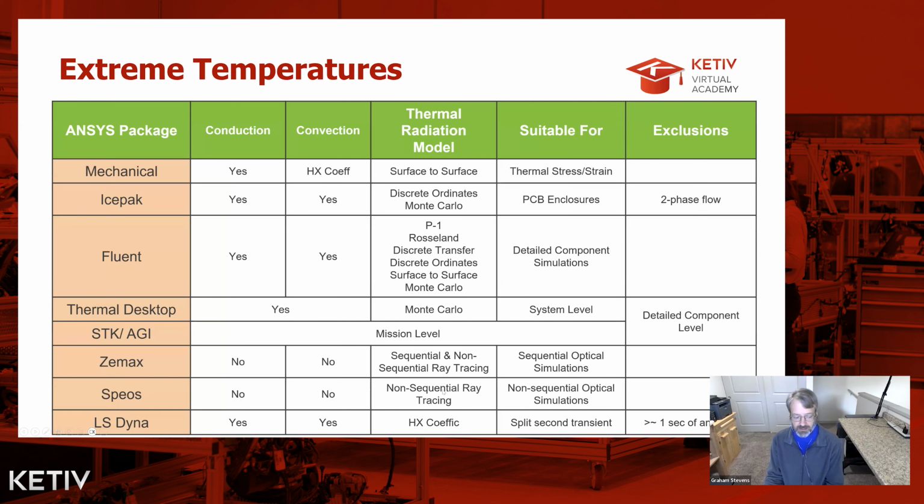And then finally, LS-DYNA has only heat transfer coefficient capabilities in terms of its thermal radiation. But if you are doing some sort of split-second transient, that is where this analysis shines relative to doing extreme temperature analyses. So right after launch might be a good time to do an LS-DYNA analysis.